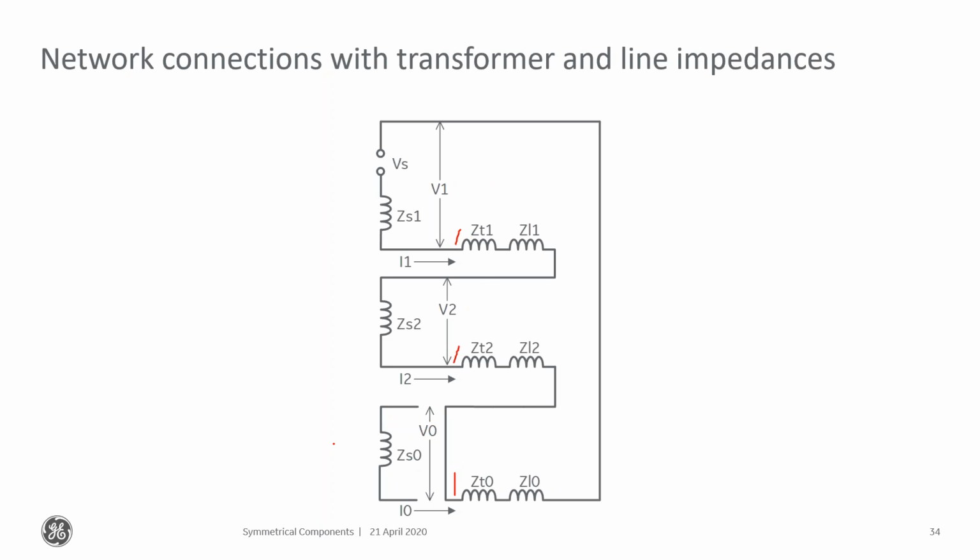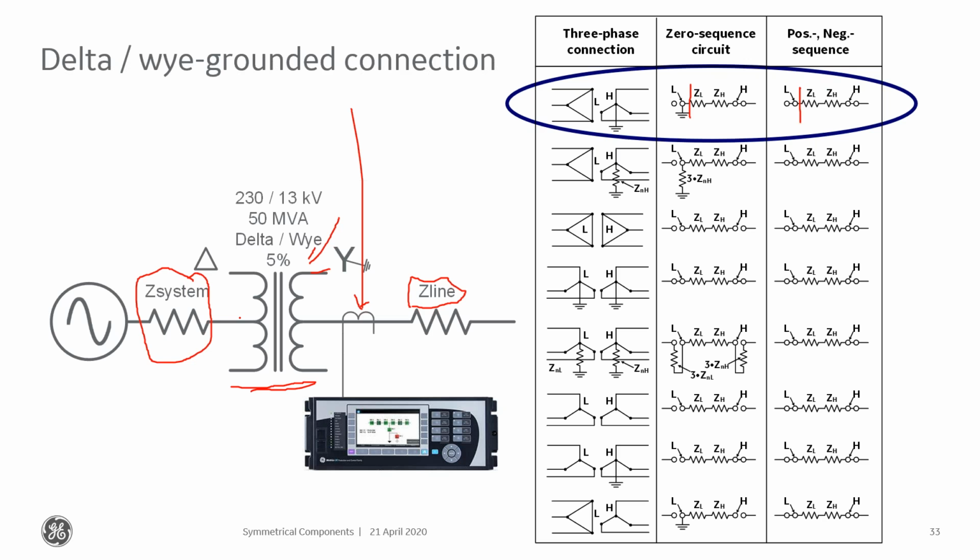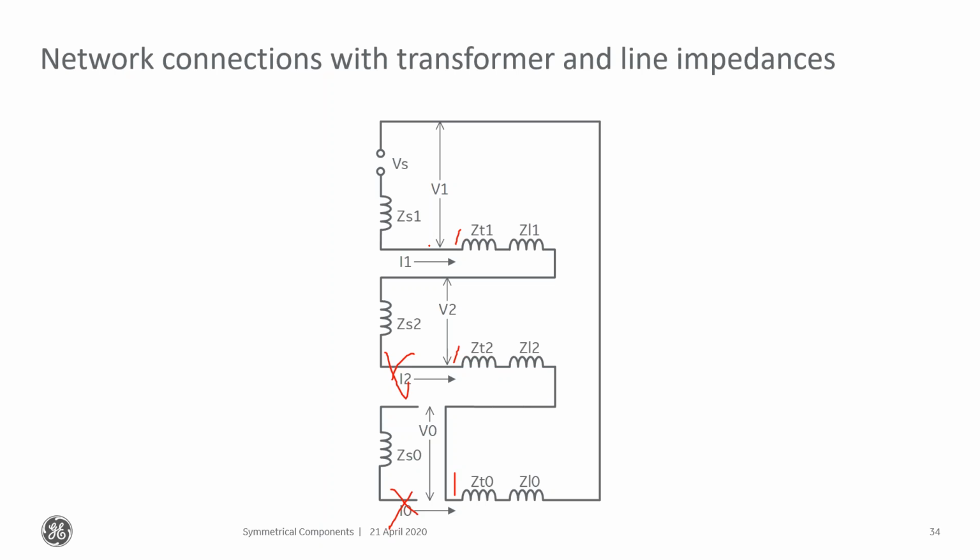Now, what's important to note is if my meter location was on that delta connected winding, so if my meter location is right here, I have a different scenario. That means my meter location is here, here, and here. Now, I can still provide zero sequence quantities to that fault on that distribution system.